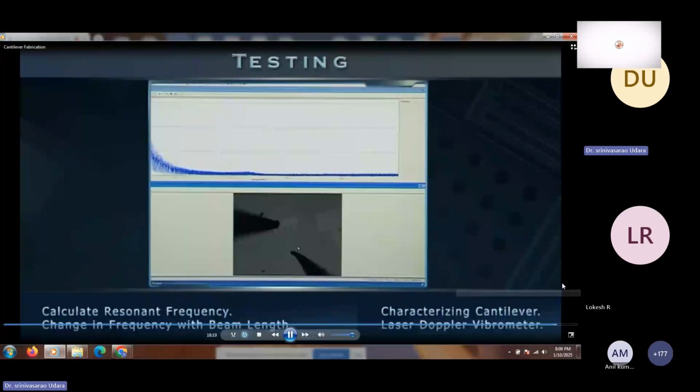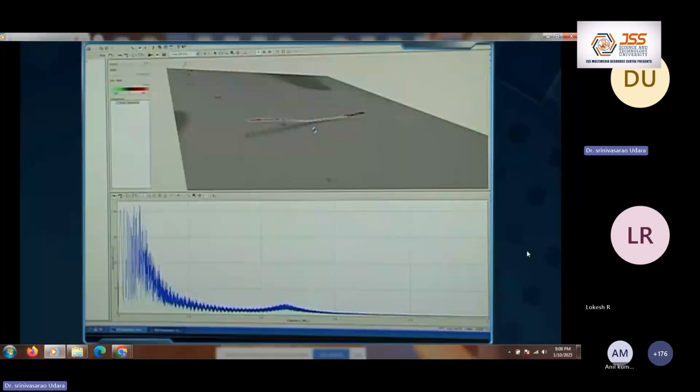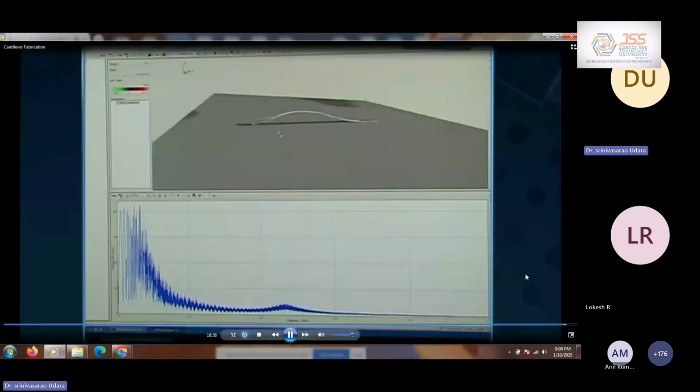The vibrometer picks up resonant frequencies of the fabricated cantilevers and displays corresponding velocity peaks. This confirms that our team has successfully created functional cantilevers. The vibrometer software also allows identification of vibration modes, such as first and second, by synthesizing a 3D animation from data taken along a user-defined path.